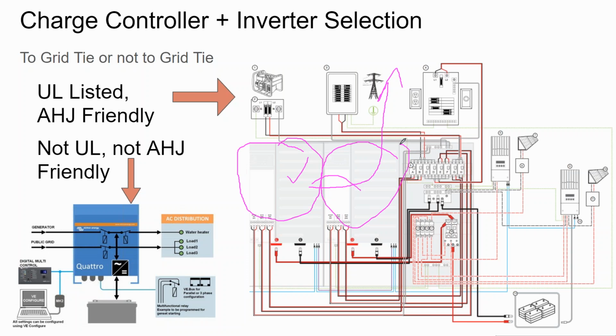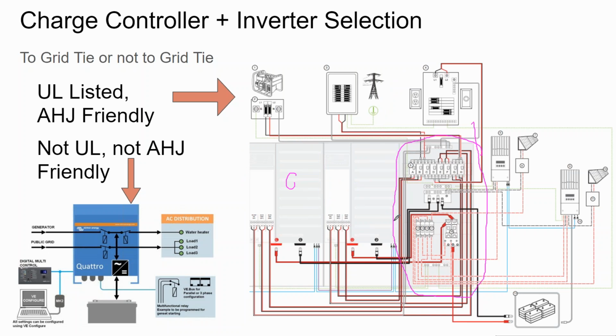In fact, a lot of people prefer double redundancy. But just keep in mind, it's not just the cost of the inverter, it's the cost of the balance of system material that really gets you. By the time you buy one inverter shell and then another inverter shell so that you can do whole house power and not just a critical load or a small amount of power, and then you buy the switch gear that's required to run both inverters in parallel with each other, that's when the cost of these grid-tied battery inverter systems really starts running away with you.